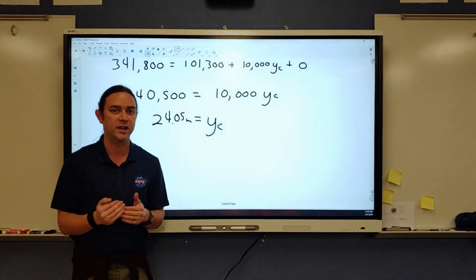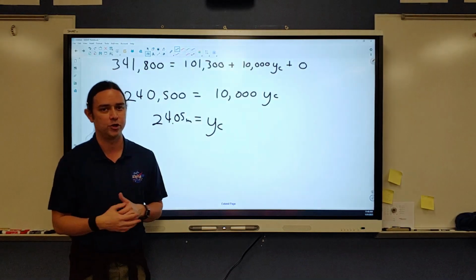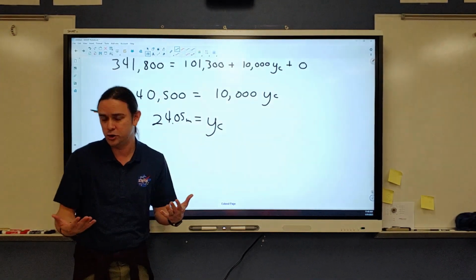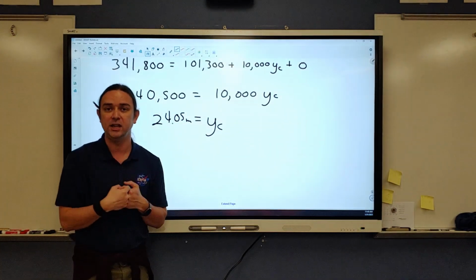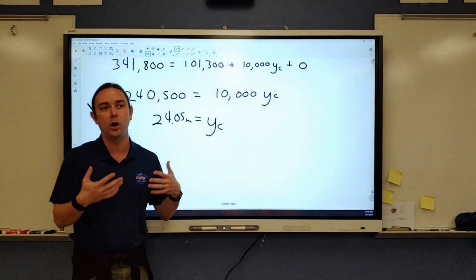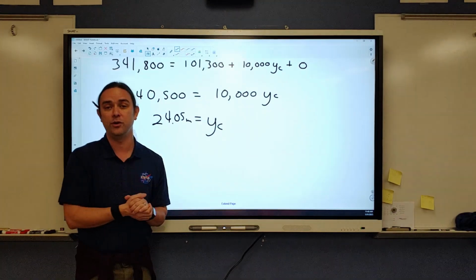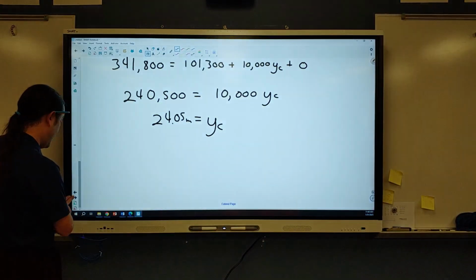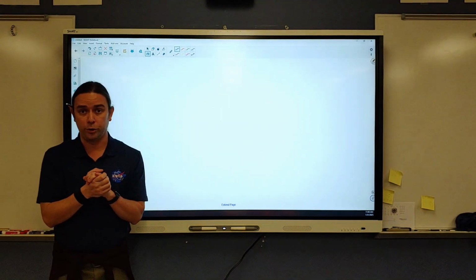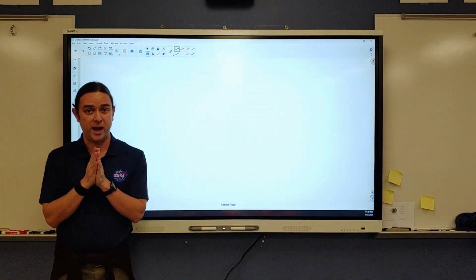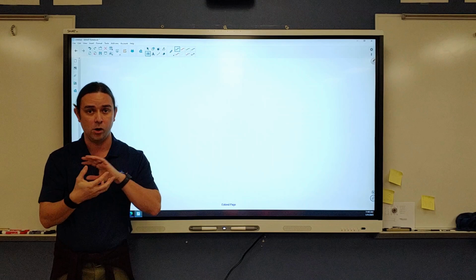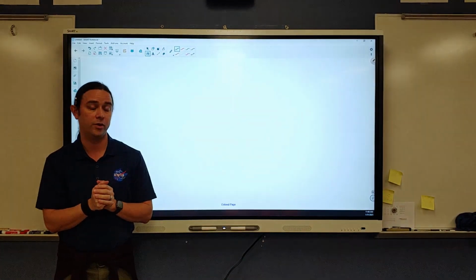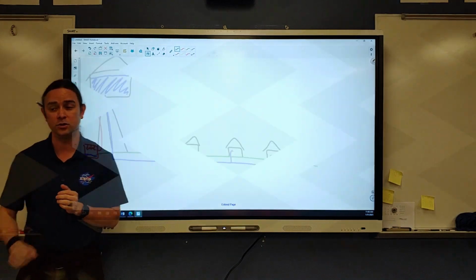We describe them as a drop in pressure from frictional losses, but when we understand that pressure is an energy density, functionally, friction is going to take some of that energy, and therefore we would have less energy per unit volume, and therefore lower pressure. Okay? That's the sample problem that I wanted to work through with Bernoulli's. We're going to be back in just a moment to finish up and tie all of this together and get a little bit of understanding of why we do things the way that we do with our modern plumbing system. So back in just a moment.